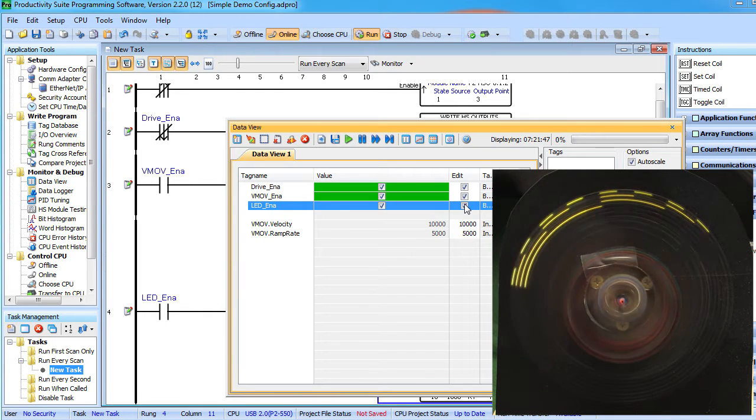And sure enough, you can see the pattern of the 4 LEDs we were driving from the first HSI module. LED 1 is toggling every step, which was every 100 encoder steps. LED 2, every other step, etc. This is so cool because you can visually see what 100 encoder counts is. And you can see that of the 4096 encoder counts in 1 revolution, the pattern is stopping at around 1600.